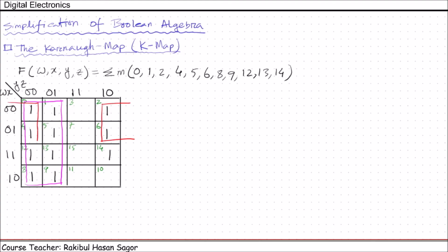side by side. These ones are covered by another box, but if we can take these ones to make the other remaining ones have a greater box, then we must consider that. Otherwise, the function will not be the simplified version. Finally, for the single one, what is the maximum number of ones can we take? We can take 2 or we can take 4 even. So we'll go for 4. So we'll take these 4 adjacent cells.